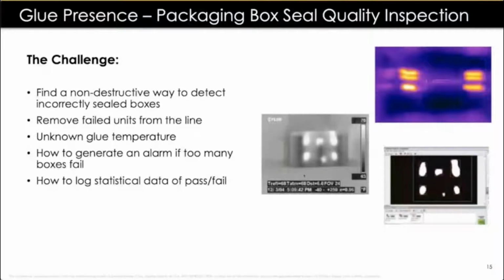And then the last thing is, do we have the right spaces in between each of the blobs to not oversaturate that particular product? Check. Once we've checked all those three parameters, we're able to come back to the equipment PLC and say, yes, you have a pass part, you have a good part, and proceed.